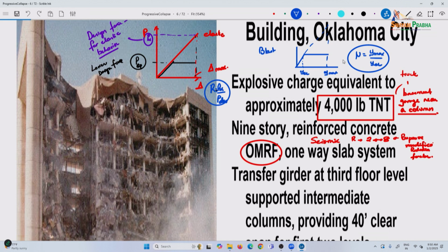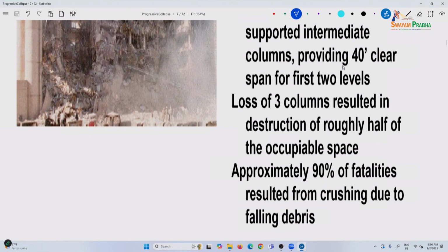In fact, there is a moment you see high mu values, we haven't talked about it or addressed it in any way. But if you see high mu values, which means that you have to take a lot of steps to ensure ductility, especially if it is concrete structures or steel structures. Connections should be ductile. There is a lot of development length considerations. You can't have brittle concrete. Concrete should have a certain amount of ductility to it. There are a few things I'll maybe mention later on.